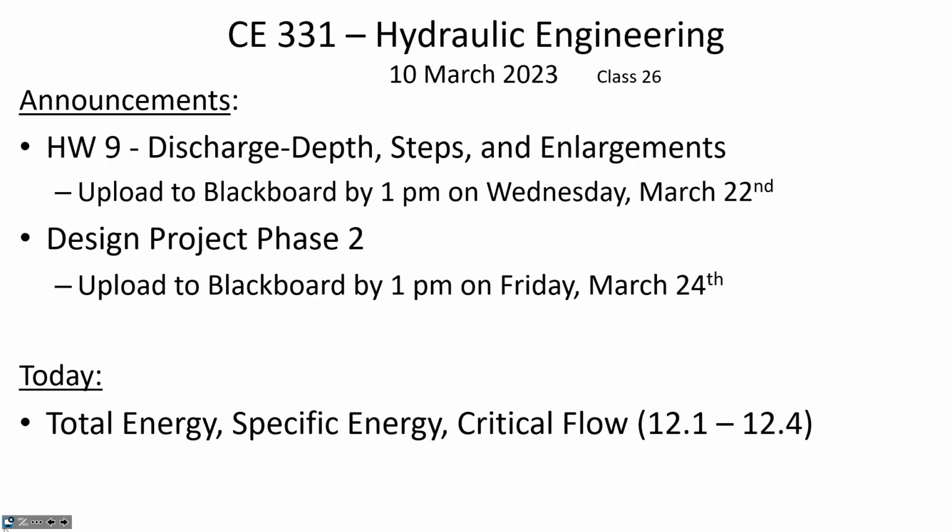What's that? The homework that was due today, were the last few questions, have we gone over that yet, like the critical depth and stuff? Yeah, critical depth, remember, is you'd set the Froude number to 1 and solve for y. Okay. We'll talk more about it today, but the thing that I think will be new information today is talking about critical slope. And there wasn't a critical slope question on the homework, was there?